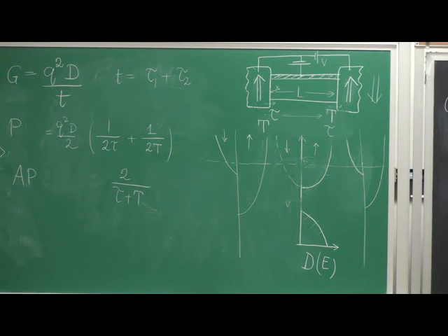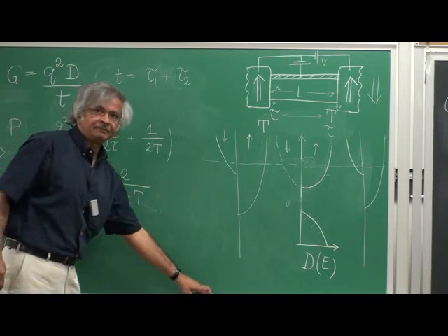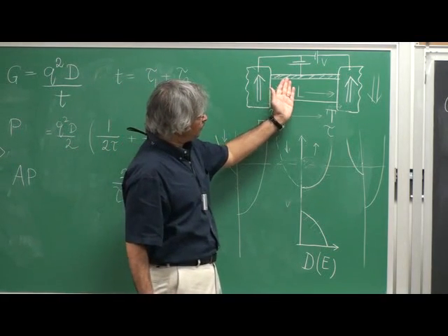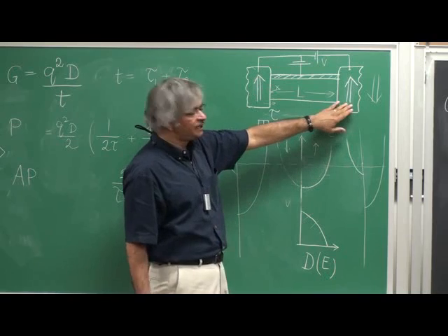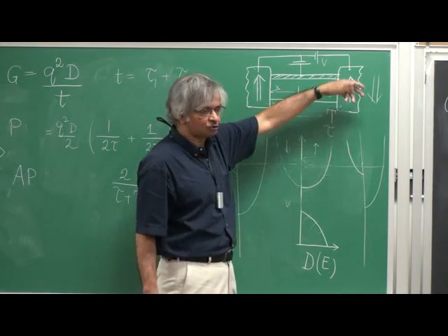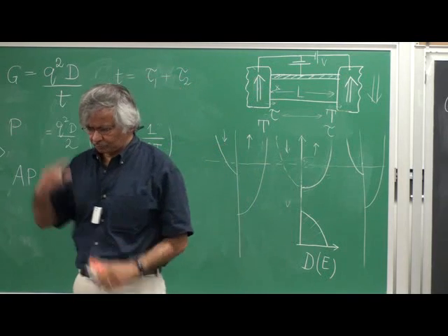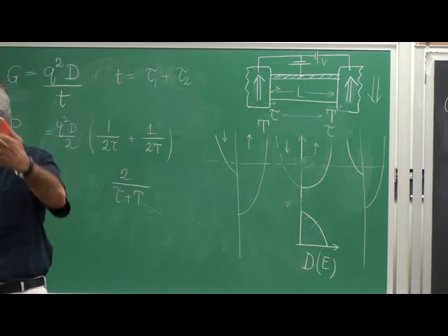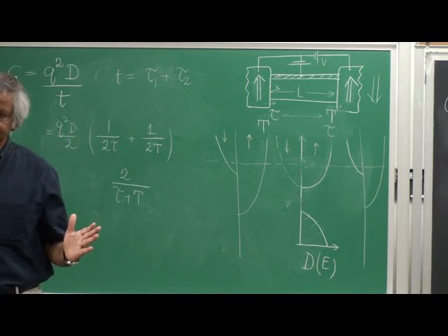And one thing that kind of followed from that in the next 10 years is something called spin torque. And the spin torque device, the way it worked was something like this. You see, with the spin valve device, you can read the information, but you still cannot write it, because if you want to actually switch the magnet, the way you do it is you put a real coil around it and create a magnetic field. That's the only way to turn a magnet, 10 years ago at least.